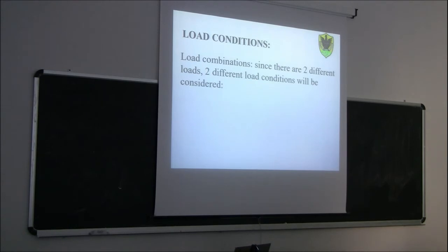And of course, if you have two loads in the same condition, you have two values of K mod. You need to take, remember, the maximum value of the K mod. You have to take the maximum, okay? Meaning that it's not sure that the most critical load condition will be the full one.